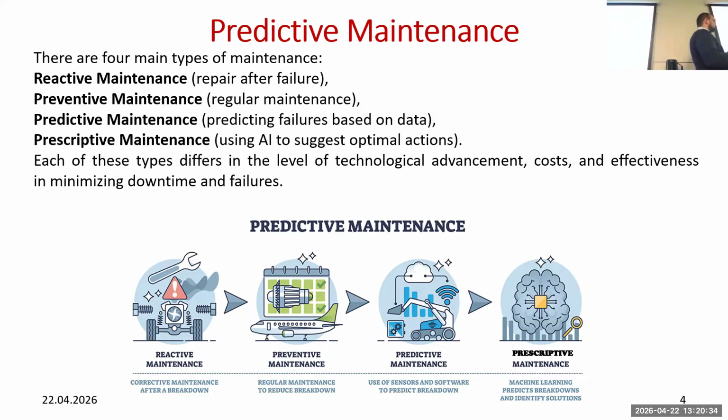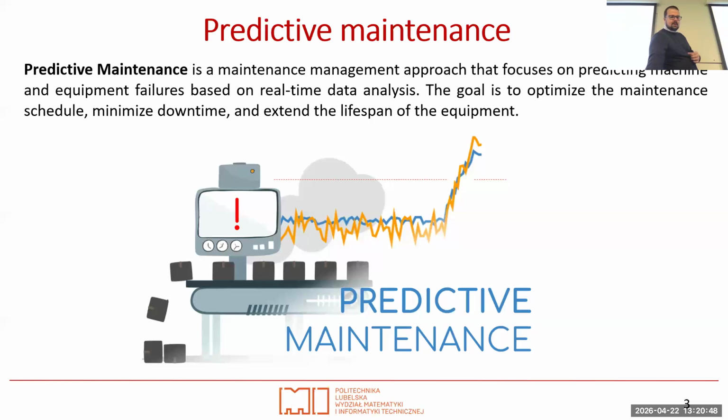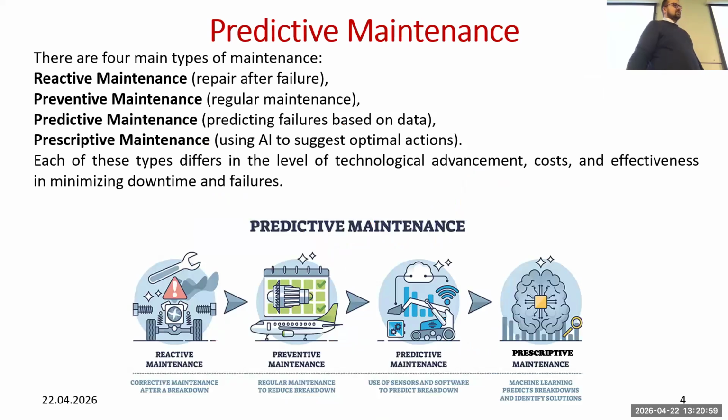So, with predictive maintenance, for example, we have one feature, like the RMS value, and when everything is fine, it is on a constant level. We calculate it one by one, and we are under the level of the damage. Once something has happened, it propagates, and this RMS value, because of the increased energy in the signal, also increases.